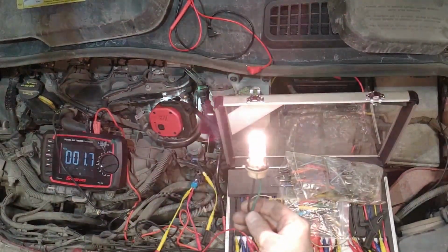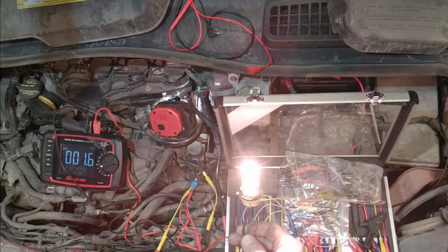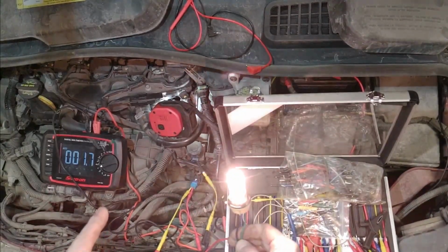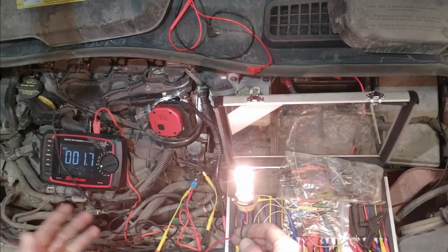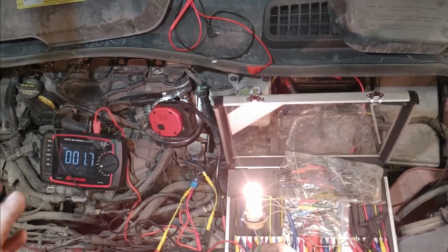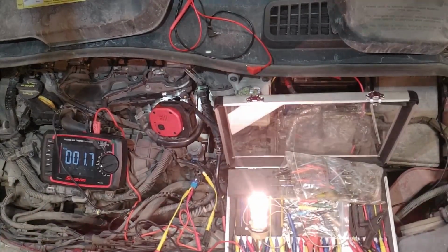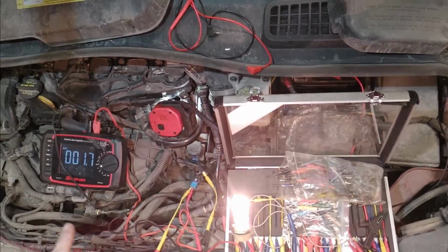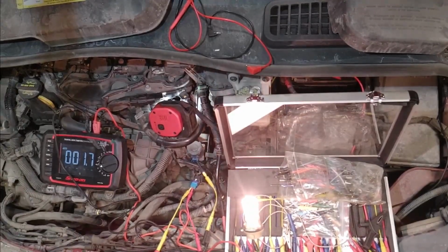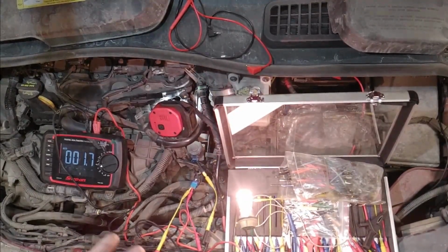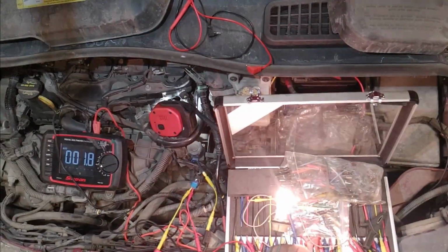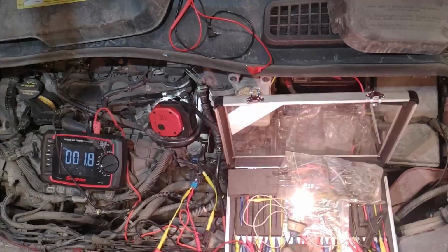So what's that telling me? That's telling me that everything from my PCM, my control box, and everything is good. So I'm gonna go ahead and say that there is an issue with the valve. We have 1.7 ohms of resistance. What's going to end up happening is that when I get the new valve, I'm going to take the resistance of the new valve and see if the resistance is higher or lower. Now, if the resistance is higher, that's probably why it was saying that there was an open circuit on the control side. So that's it for this diagnosis right now. Like I said, when I get the new valve, I'll let you guys know, and we'll go from there.